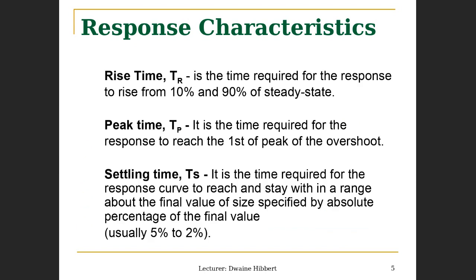Now let's define these terms. Start out with the rise time. Rise time is the time required for the response to rise from 10% to 90% of what we call steady state. In other words, the difference in time between the 10% and the 90% points is the term often used for the rise time. Okay, that's rise time.